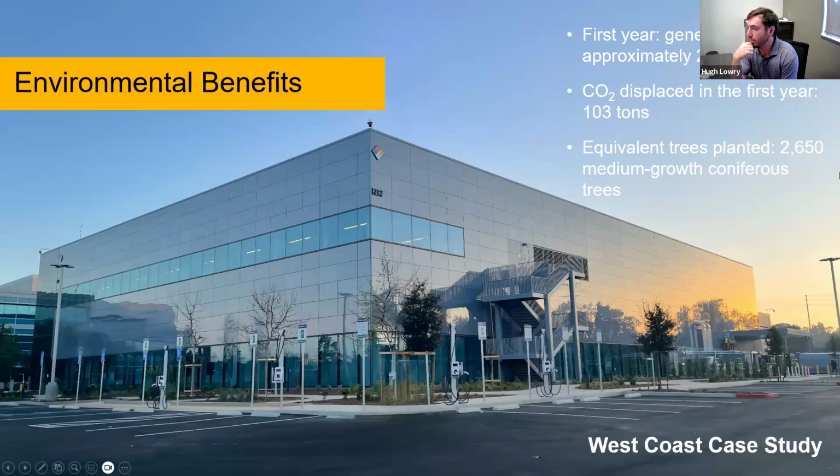So if I'm looking at that staircase right there, basically behind that staircase, we put an ACM product, primarily because there's going to be a lot of shading coming from that staircase. So it didn't really make sense to put solar panels behind it. But secondary reason for that being there had to be penetrations into the building to support that staircase. And obviously penetrations don't work well with tempered glass, but they work great when you have a metal panel.